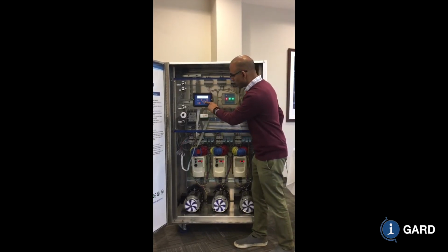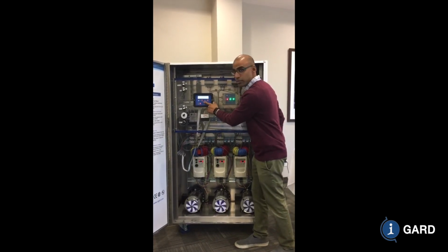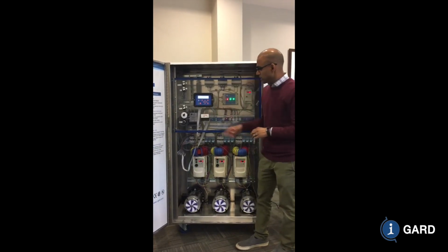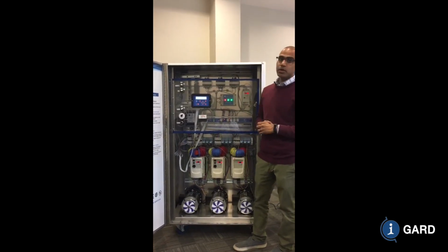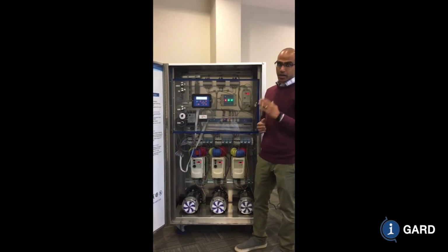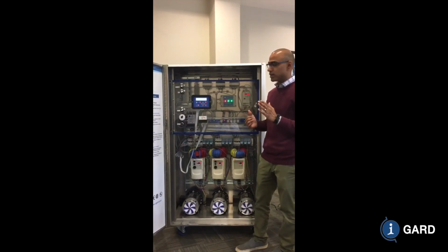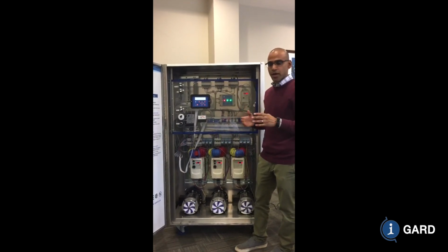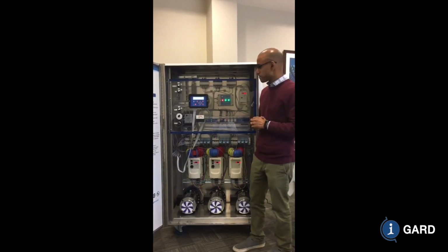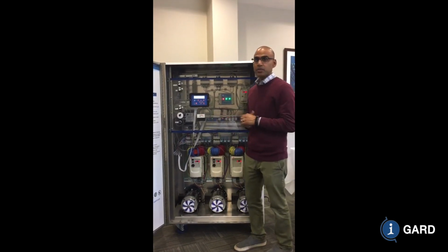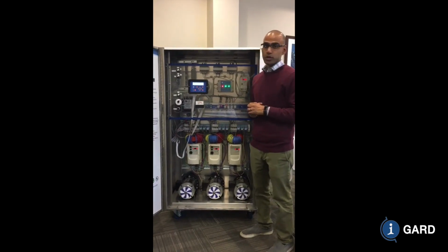When I go a page over to employ pulsing, I hit the left button and turn pulsing on. Notice that the needle goes back and forth. What I'm doing with pulsing is changing the fault current by cutting it in half once a second. That pattern appears in the entire ground fault circuit, the ground fault path. That pattern is what I look for when I'm looking for a ground fault.